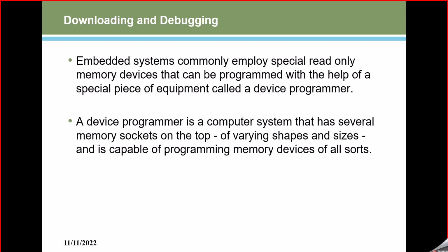These are all downloading tools, and debugging is nothing but where you need to check whether the code is working or not. Say you flash the code inside the microcontroller, a microprocessor. You start giving power supply to the controller, a processor. Now the processor should start executing your instructions, right? It should come inside the main function. Inside the main function, it should look for any local variables initialized, or any functions called. Those things will be verified and it will start executing inside the while one.